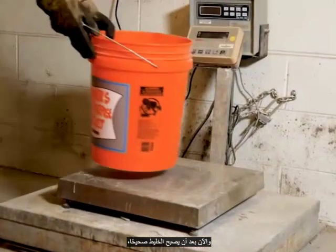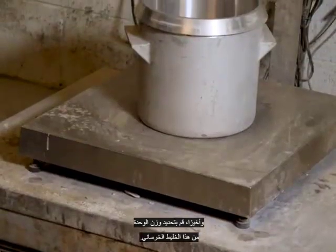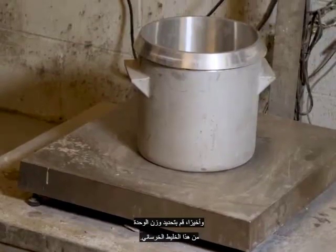Now that the mixture is correct, weigh the remaining aggregates and record these values in the datasheet. Compute the actual amount of coarse and fine aggregates used in the concrete mix from the initial weights. Finally, determine the unit weight of this concrete mix.